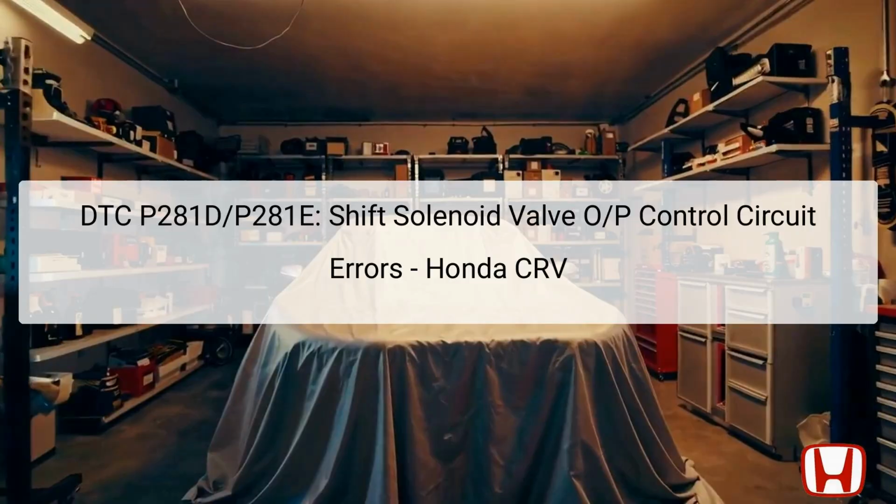DTC P281D and P281E are diagnostic trouble codes indicating issues with the Shift Solenoid Valve OP, specifically relating to its control circuit. This valve plays a crucial role in controlling transmission fluid pressure, thus impacting overall vehicle performance. DTC P281D indicates a low voltage situation, while P281E highlights a high voltage scenario within the control circuit of the pressure control solenoid H. These codes usually arise due to electrical issues rather than mechanical failures.